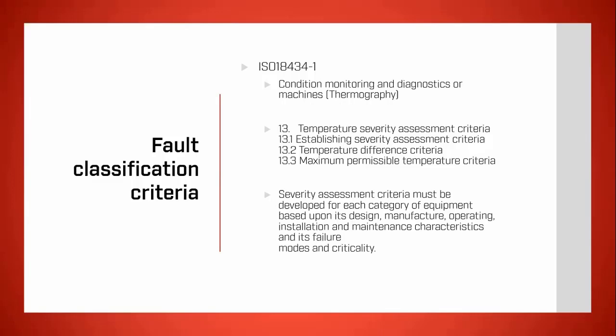Applications should include temperature rises of critical machines, mechanical components, bearing temperature rises, electrical supply, or connection rises. Could include fluid leaks and losses, or even a number of tubes clogged in a fluid heat transfer type equipment. So within chapter 13, if you can get your hands on this standard, have a look at it, because it will really help to establish severity assessment criteria.